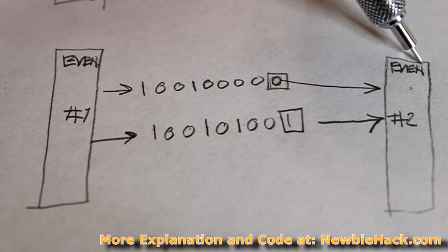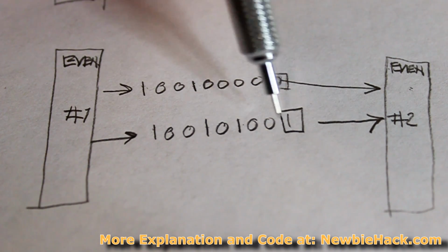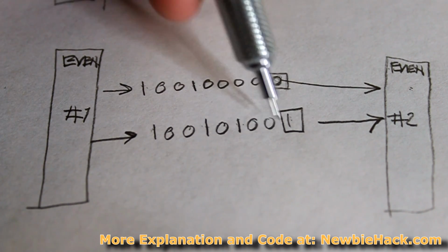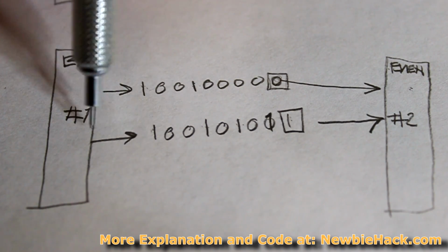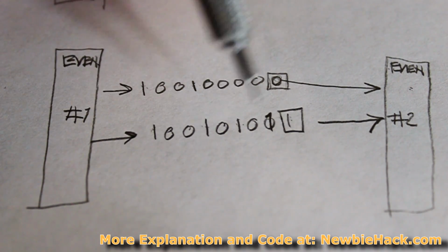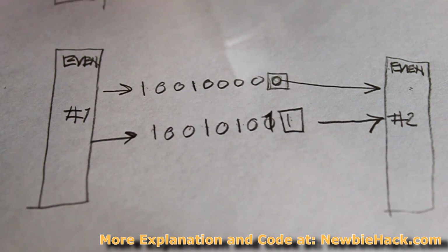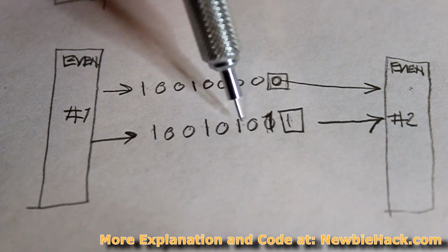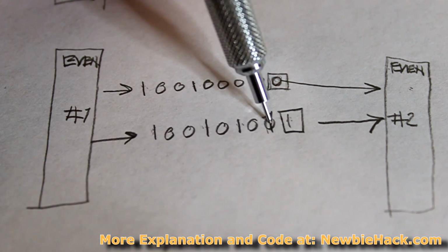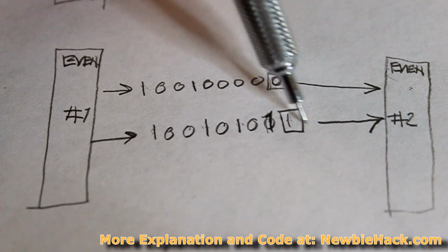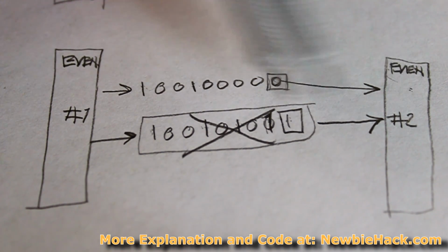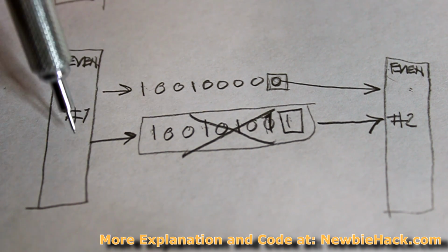Over here, this microcontroller is going to check to make sure that there is an even number of 1s in here. And if there isn't, that means that there is a problem, because let's say there's a 1 in here somewhere in the communication line between these two microcontrollers, and a 1 was added somehow because of some interference from a motor nearby or something, caused a 1 to be here. Then that means that there is a 1, 2, 3, 4, 5 1s in here, but this is set at even, so that means that this must be incorrect. And then since the error checking is happening, this microcontroller has to resend the information.